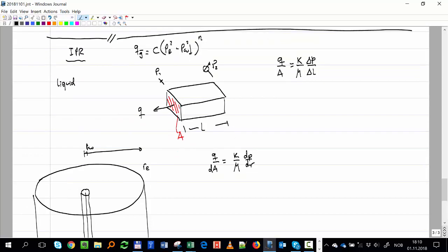Actually, just a few things before we go into that equation. This equation pretty much tells you that this is the local rate. And that local rate, if you divide by the area, what do you get? Velocity, right? But not really. Remember, this is a piece of porous material, so it's not circulating through all the area. It's circulating only through the pores of that face.